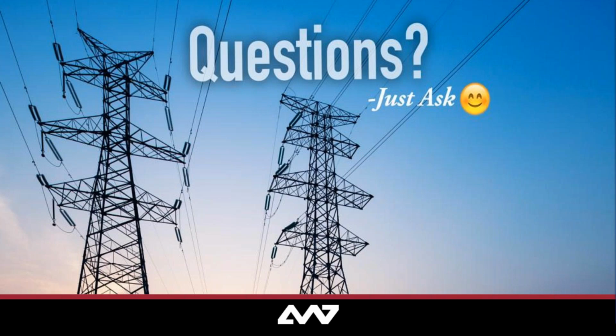101 would be over a serial link. It can either be balanced or unbalanced. If it's unbalanced, the master's polling, so there'd be no need for keep alives. I mean, that's the equivalent of a keep alive. It's constantly talking. 101 balanced, there are no keep alives, but it's also not over TCP. The point of the keep alives was to make sure that the TCP connection doesn't go down and need to be reestablished. So 104, yes, there are link layer keep alives. They're called test frames.